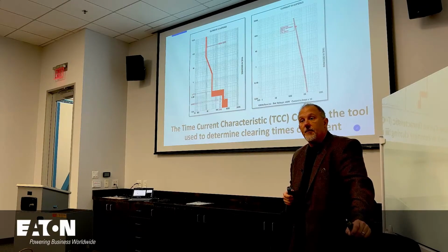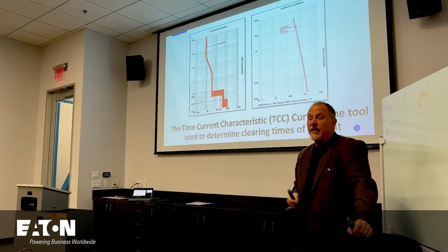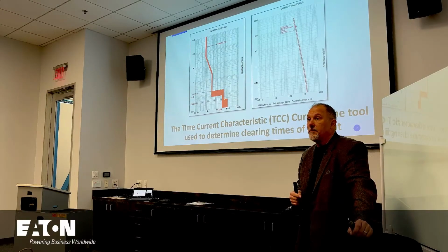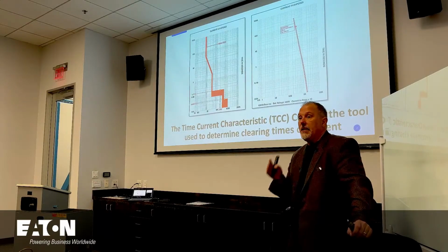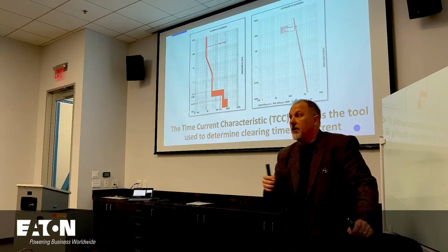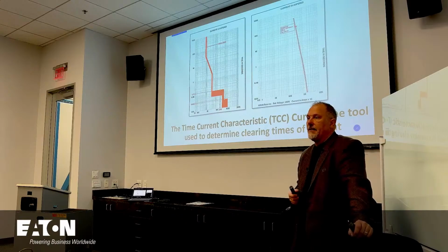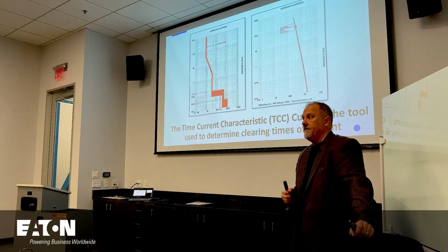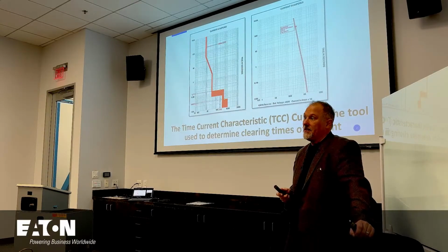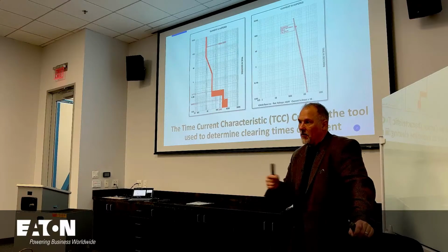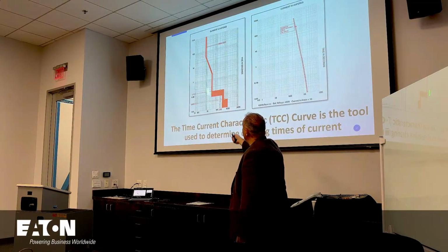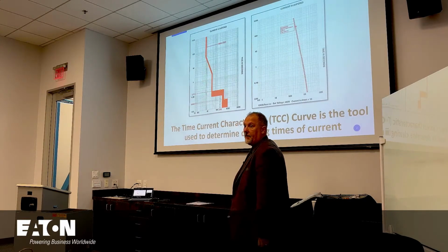And it works off of the three-phase voltage fault current value not exceeding a certain number. So for panel boards, I believe it's 25,000 amps. Anything above 25,000 amps, you need to have a calculation done. But if it's below 25,000 amps, then you can use the PPE category method. But what did we say? Not the high fault currents that get you, the low fault currents, right? The lower the fault current is, the more chances I'm in this long time region from a clearing time perspective.